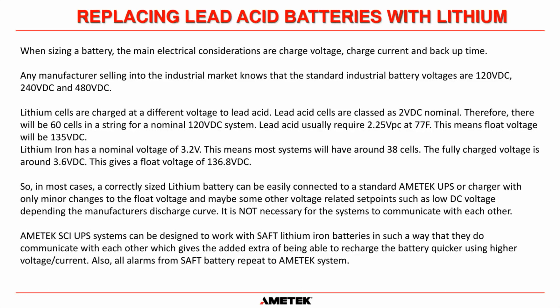Okay, and if you know anything about lithium ion batteries, they all have a BMS inside, which is a battery monitoring system. Because for lithium, you need to monitor the voltage of each cell, and you need to try and keep each cell at relatively the same voltage.